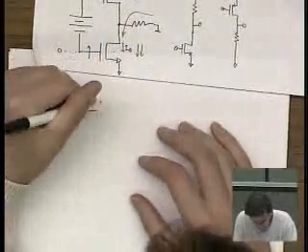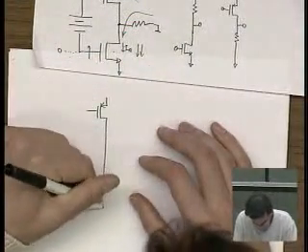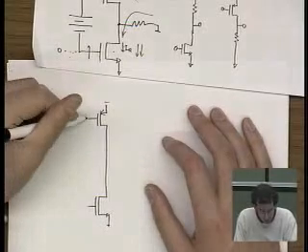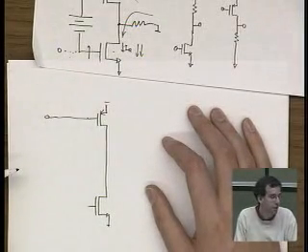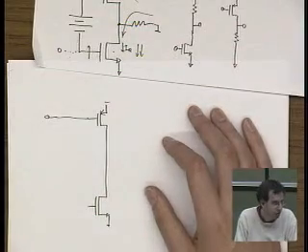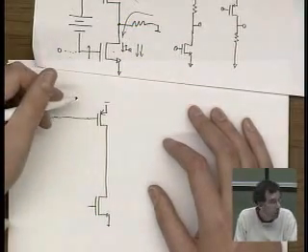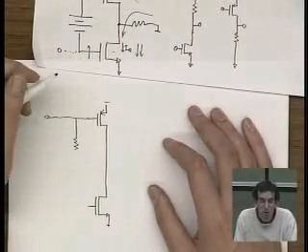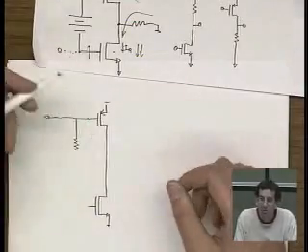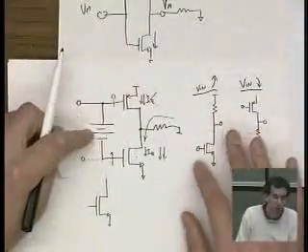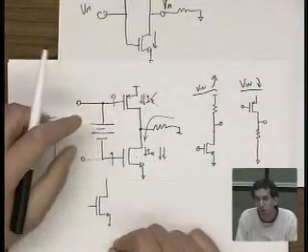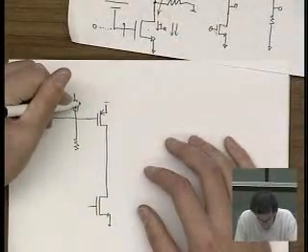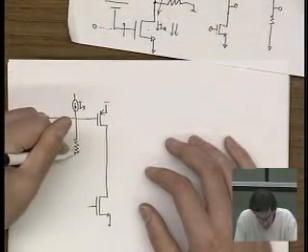So let's say we've got this is our device, and we want some battery. And let's just assume for the sake of argument that we're driving it from the PMOS. No reason why that's the case, but I'm just doing that. It could be from the NMOS. So what you can do is you want to create a battery. So the question is, this is what I was talking about in section. How do you set up the biasing of this battery voltage in such a way to get the devices where you want to operate and to do it independent of voltage supply? So this is sourcing some current IX.